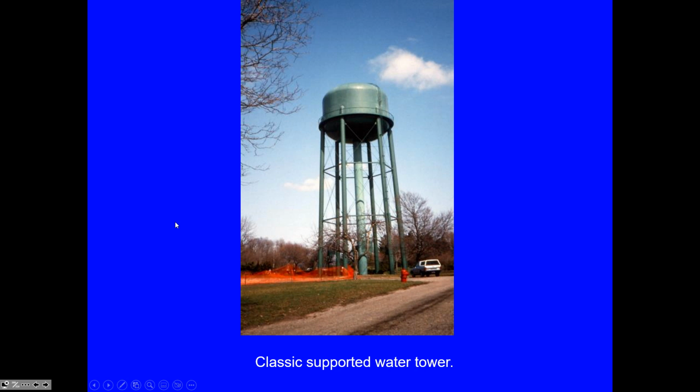So in this example we just worked, we found that during the max hour we're going to need 46 liters per second, but overnight we only need 4 liters per second. So you wouldn't want a pump running all night long that's sized to provide 46 liters per second if during the evening you only need 4 liters per second. One way around that conundrum is to bring water up to the tank as needed, allow the pump to cycle on and off, and then the pressure in the network depends just on how highly elevated the tank is.